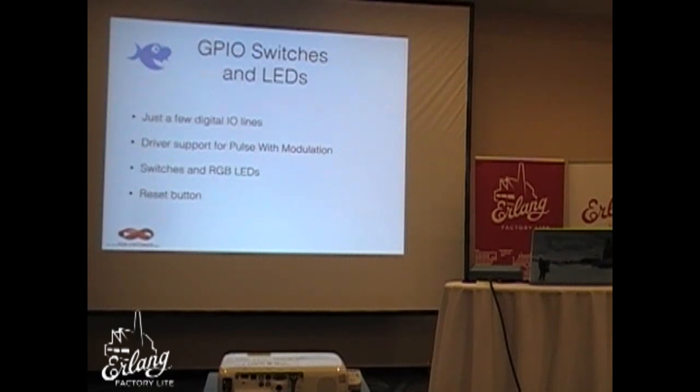One example of using this is controlling some LEDs. If you have an RGB LED, you can normally show like 7 colors or turn it off. But with pulse width modulation, you can control the RGB channels completely dynamically and get the whole color spectrum, basically. So this is really useful also for servos and other motor controls and such.